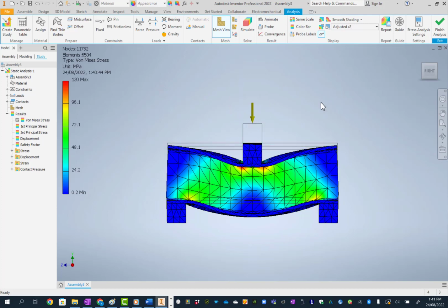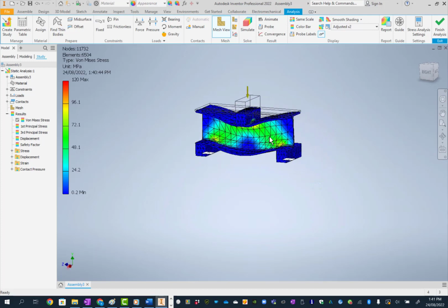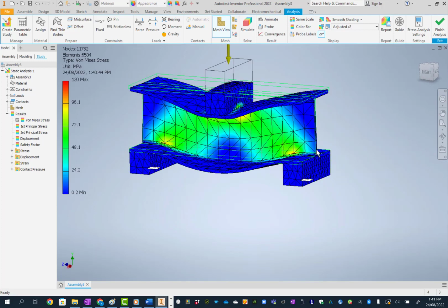One other thing just to note for this one. What you can see is that for shear, most of the stress from shear is in this web. Remember, the vertical one was called the web. And there's not much stress because of shear in these flanges. The green colour is the higher stresses. Blue means there's no stress at all, or not much stress. So you can see shear is carried by this web element.